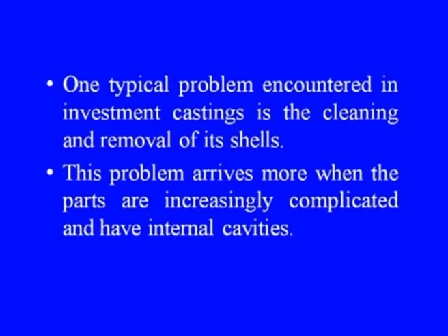Let us discuss some more issues which have been discussed only in recent times regarding this particular process, investment casting process. One typical problem encountered in investment casting is the cleaning and removal of its shells. This problem arises more when the parts are increasingly complicated and have internal cavities. As the parts become complex, cleaning those complex profiles is very difficult.